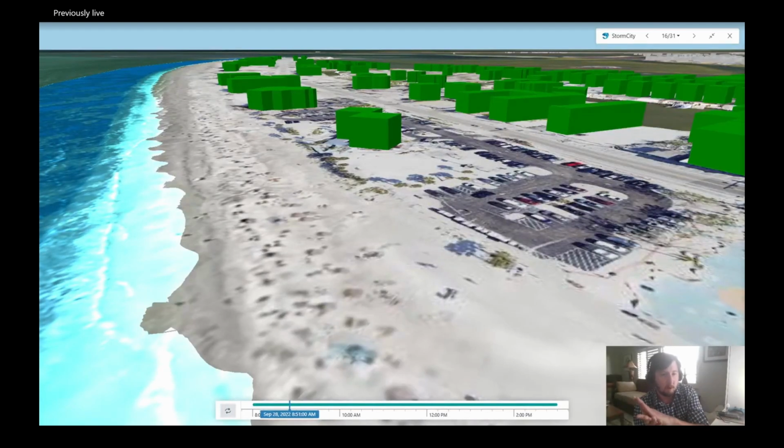David asks, would you recommend using an adaptive mesh to define rivers and roads? Not necessarily. For a river, I would recommend using a directional mesh, or let me just double check what they call them. There's a rectangular mesh that you can use for a road that's going to be better for the road, and then there is a directional mesh that's going to be better for a river.